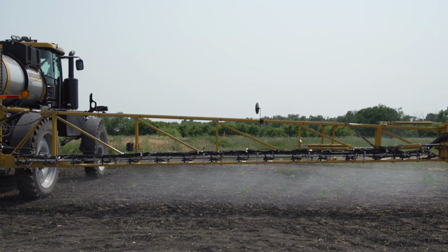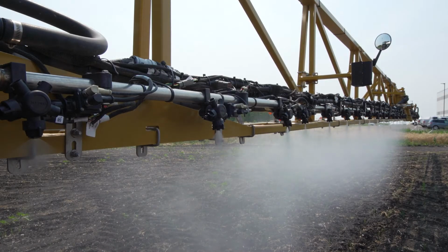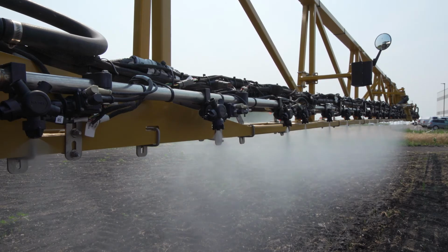Okay, now in this third example, we have a section of nozzles where we have simulated a low flow nozzle and a nozzle that has higher than normal flow. Now, why would higher flow happen? This can happen because maybe you've been using this nozzle for too long and that orifice has started to wear out, so the hole is actually getting bigger. And because of that, at the same pressure, it's going to output more flow than its neighboring nozzles.